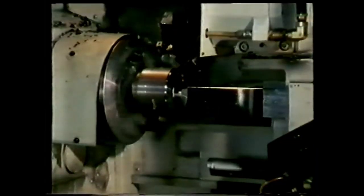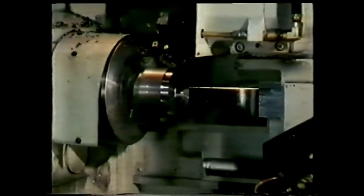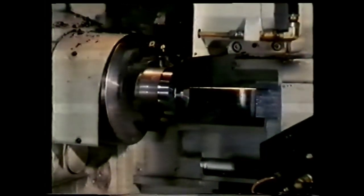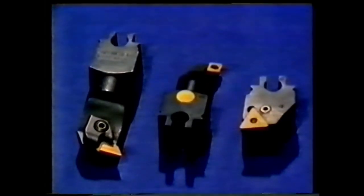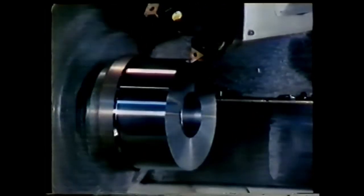Although inserts are easily changed, with the new CNC machines in use for high production batches, even these changeover times are considered slow. A new system is that of block tooling. The block tool has an insert already fitted and can be changed in a matter of seconds by simply slipping out the old tool and fitting in the new. The old insert can then be changed while the machine is cutting with the new tool, and so a minimum amount of time is wasted.